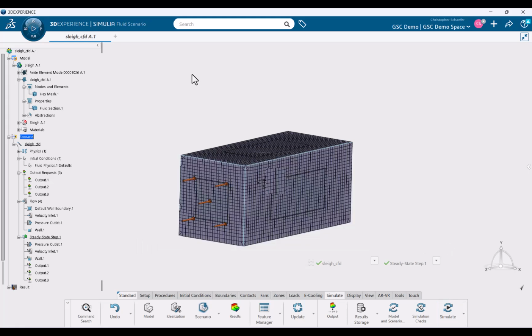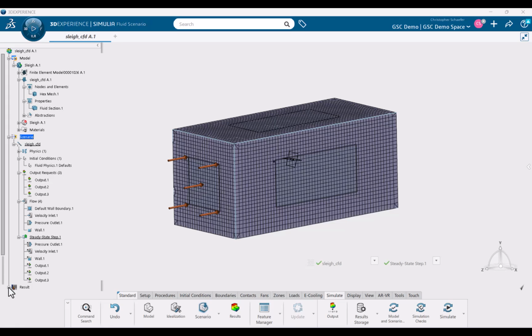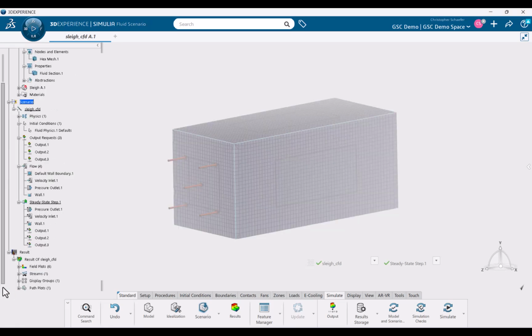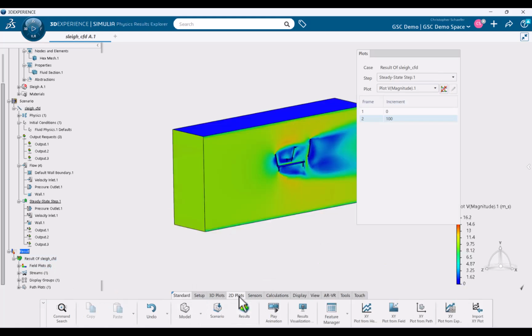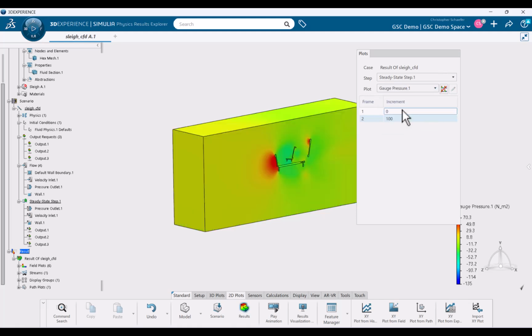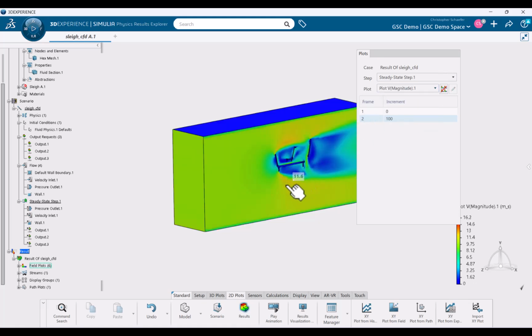When I solve locally, I can create an interaction that influences how I post-process or look at the results. Speaking of results, common computational fluid dynamics results include cut plots, section plots, isosurfaces, flow streams, looking at pressures, temperatures, velocities, and being able to interact, such as the probe tool, which allows me to pick off data points and store those for further post-processing.